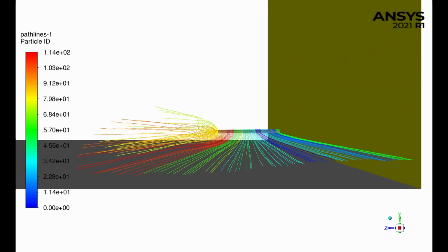Looking at the wall case now, we can see that the vertical extent of our wingtip vortice is way lower than in the free stream case. Generally, the case looks more flat, and it looks like our vortex in general is smaller. What we can, however, see as a difference is that our vortex core is curved towards the left side. It is no longer really straight as it was in the free flight case.